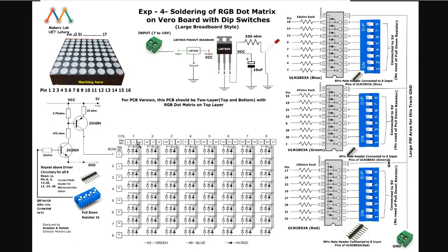So now when you have 3 over there, this will actually become a difficult one, and to make it concise, this is going to be the task that is going to be with you. Now when these are row arranged, first of all, that is the red color over there, you will take the red 8 pins coming from here and connect them with a ULN2803 IC.